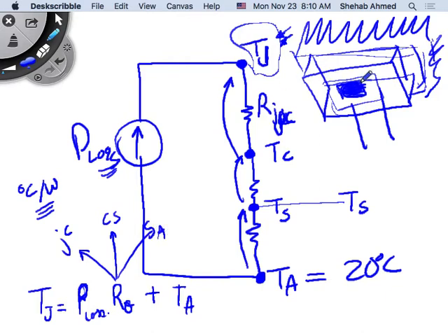So I have my junction here. It does have heat generated at the junction, right? This junction is going to try to dissipate heat to the case of the device. So there's a thermal resistance, an impedance to heat flow, between the junction and the case, right? And then this case, you can leave it up in the air, just hanging out there with no heatsink, for example.